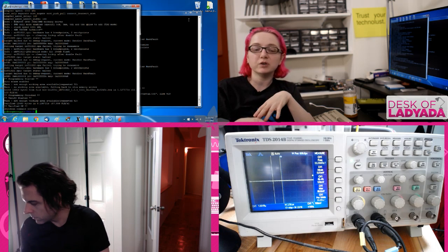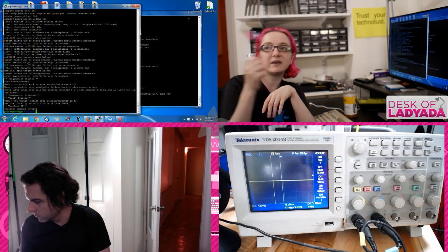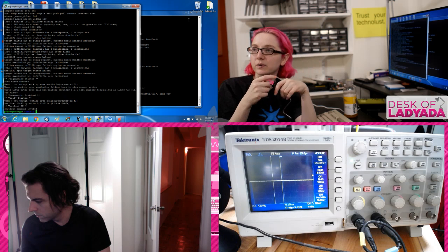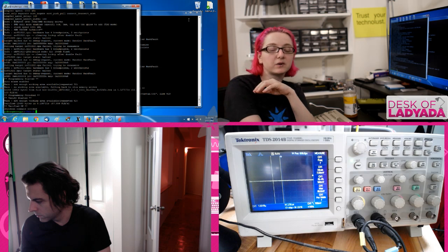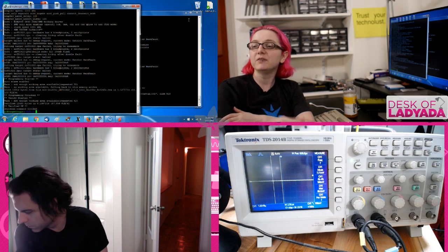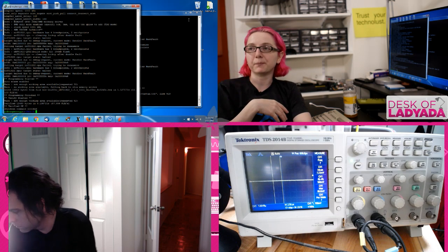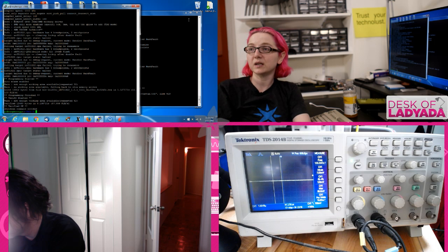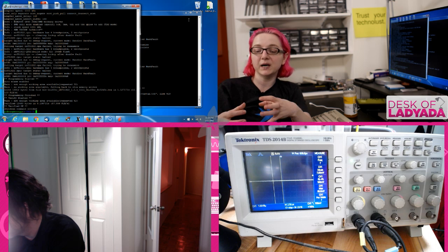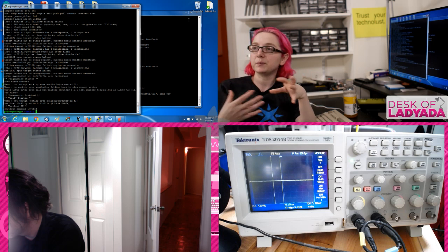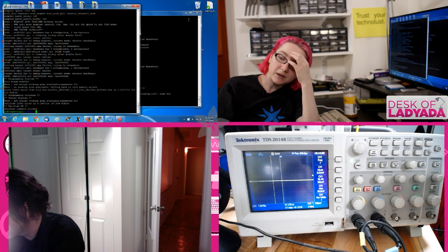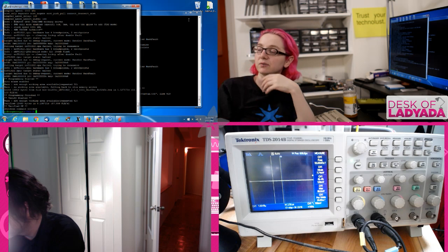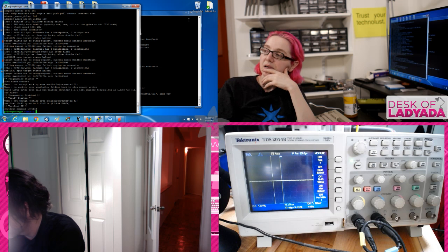but this is still handy for people even if they're only programming one chip, because let's say you don't have an ST-Link, or maybe the ST-Link doesn't work with the chip you're programming and you don't want to spend $100 or more on a J-Link. If you have a Raspberry Pi, you can program pretty much any of these chips that OpenOCD supports, and it supports a lot of them. So you can get started programming very fast, and you can set it up as a debugger, and then use your desktop computer to debug and program through the Telnet interface. So I think that's kind of neat.